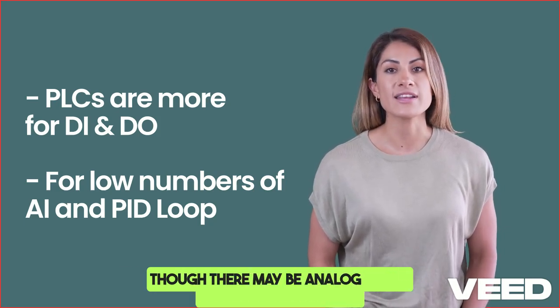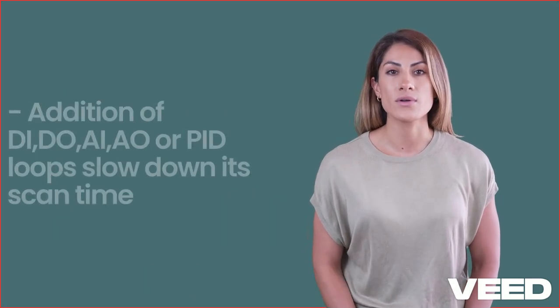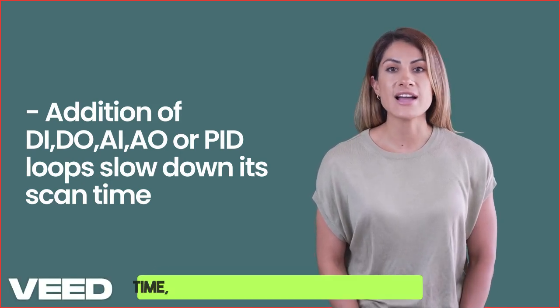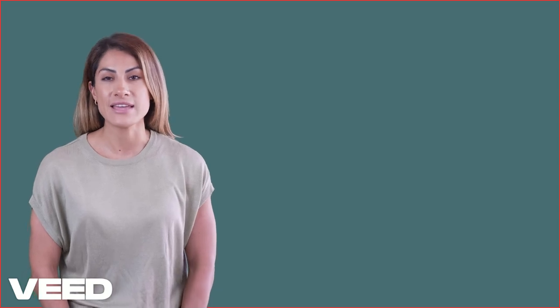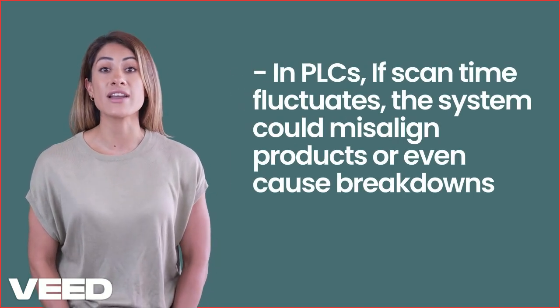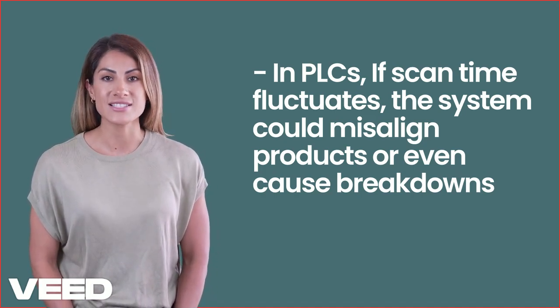Though there may be analog inputs and outputs and some PID loops as well, the numbers will be low. That's why the addition of new PID loops slows down PLC scan time every time, as it takes much processing time. For example, if a PLC is controlling a fast-moving conveyor belt, the scan time must be predictable, let's say 10 milliseconds. Every 10 ms, it reads sensors, executes logic, and updates outputs. If scan time fluctuates, the system could misalign products or even cause breakdowns. That's why PLC scan time is kept fixed.